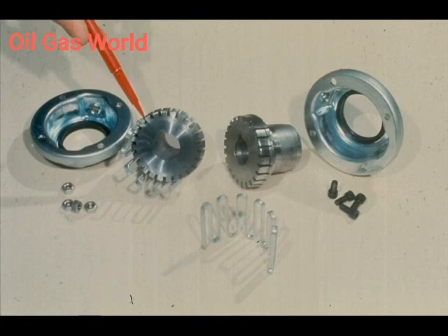This is a grid coupling. It does require lubrication since, as with the gear coupling, there is metal-to-metal contact between this grid and the slots in the hubs. However, the spring steel of the grid in this coupling adds a number of advantages.